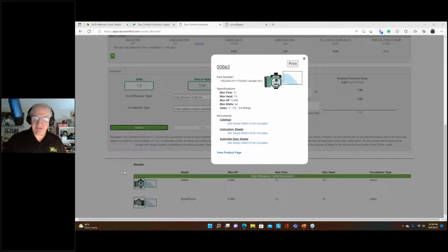Quite frankly, Jesus, this is an estimate. When we get to that point, some people like to estimate high, some people estimate low. Actually, I've seen people estimate in the 1.2 to 1.3 range, because if they know how the piping's installed, if there are a lot of fittings, you want to estimate high. If there are fewer fittings, you estimate low. It's not an exact science. It is, quite frankly, an estimate, and it's the best estimate that you can make. So I don't know if that answers your question, Jesus, but it's the best answer I have.